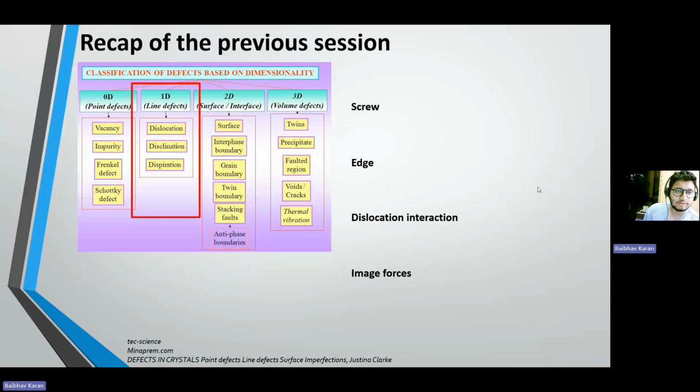It is explained that there is an oppositely signed, mirrored dislocation outside the material, which attracts the dislocation out from the crystal and annihilates it. This is what image forces are about. From this we understand that if a material goes to the nanoscale, if the material is too small, as the surface area of the nanoscale is too large, all the dislocations present go away from the surface. So the materials at the nanoscale are almost dislocation free.